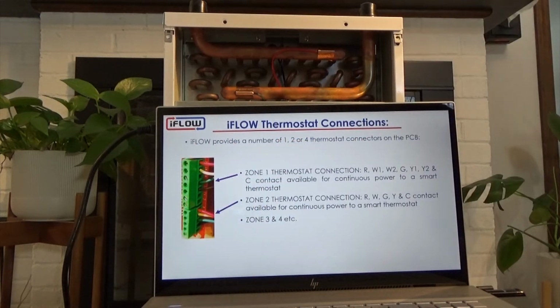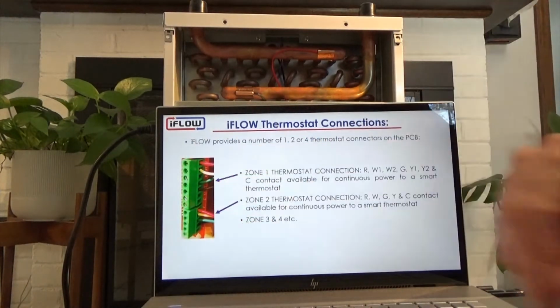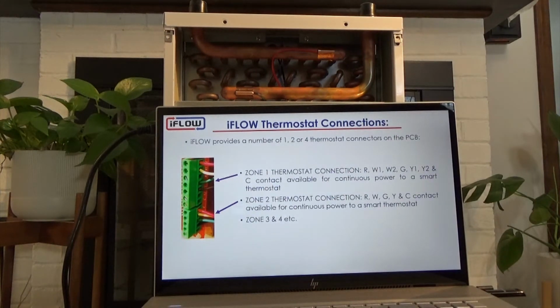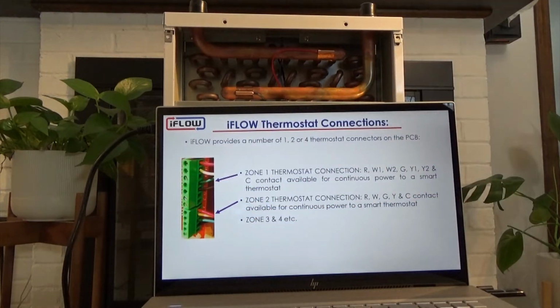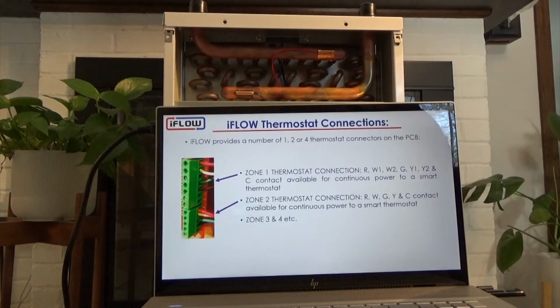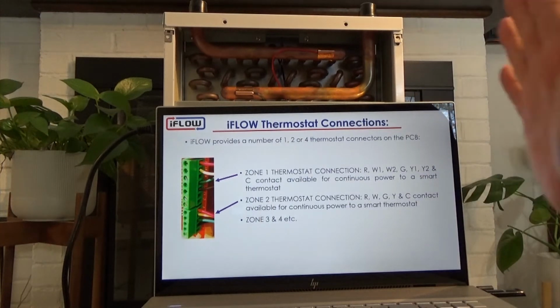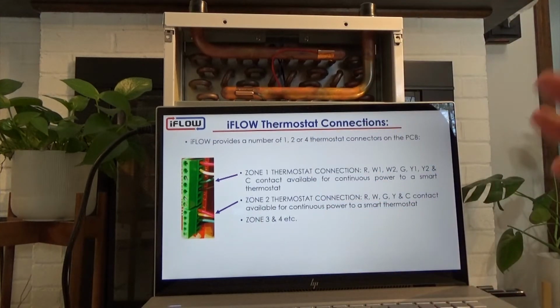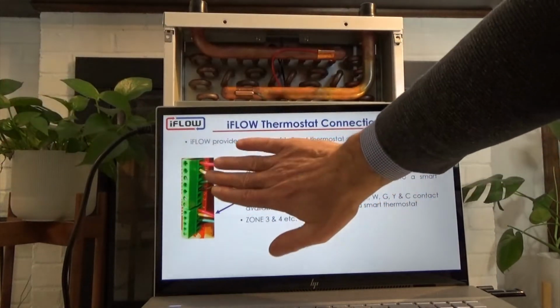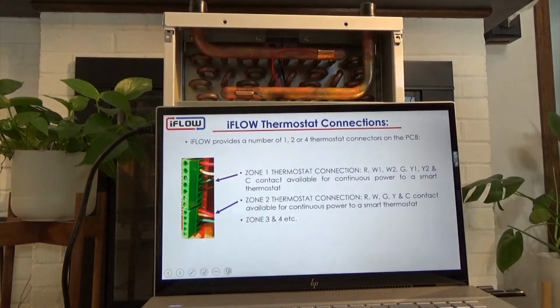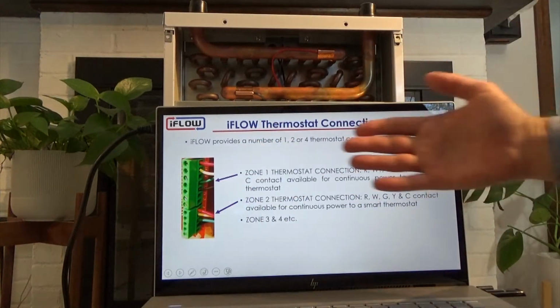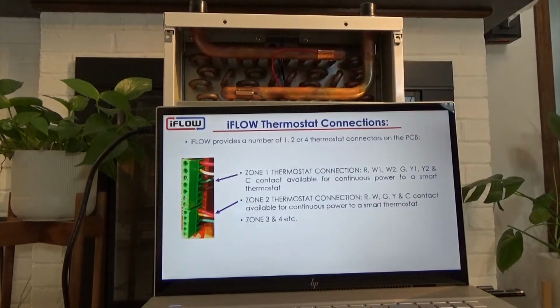When I see 2 or 3 wires connected to one contact, typically that's a no-no. You should only have one wire in because, again, we're not taking any power off this. We're running all of our outputs, for example, our AC output to our compressor, from the output contact. We're not stealing it from the Y1 contact here on the thermostat. So be sure that you just have your wiring from your thermostat in, and that's all you need, nothing out.